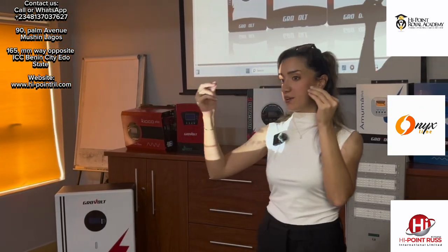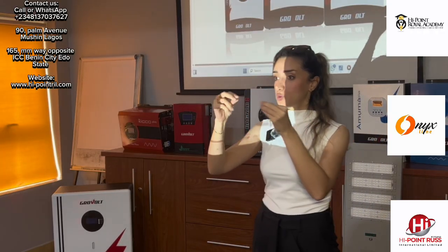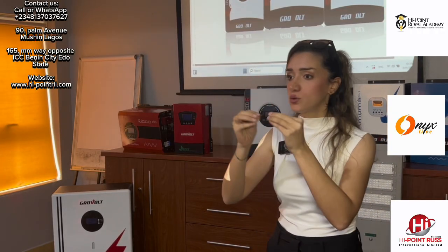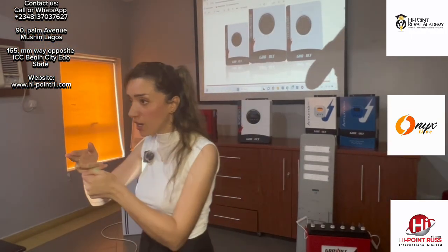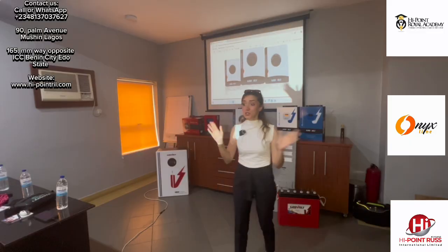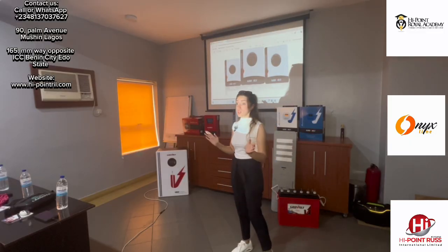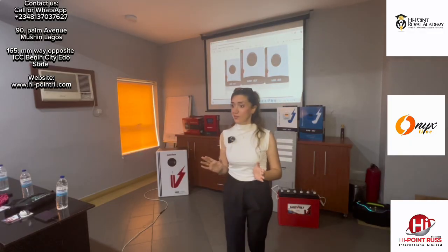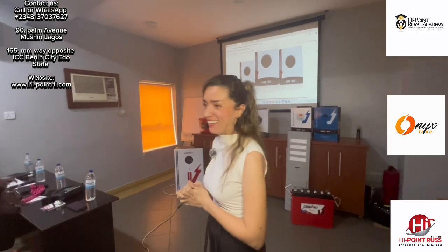Okay, DC cable. And also, when you need to connect the panel to the cable, you're supposed to use MC4. It's very necessary. Don't cut the cable and tape it. Don't do that. Please don't do that.